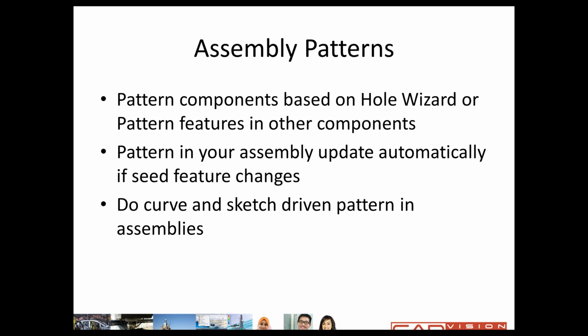In 2014, feature driven pattern is now called pattern driven pattern, which means any type of pattern can be used as a seed. You can use a pattern as a seed in your parts or in your assemblies. I don't have any examples for this one.